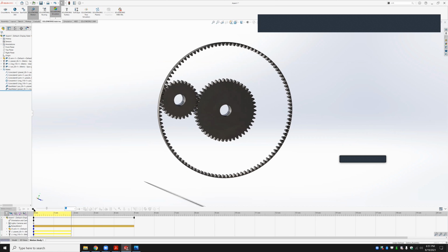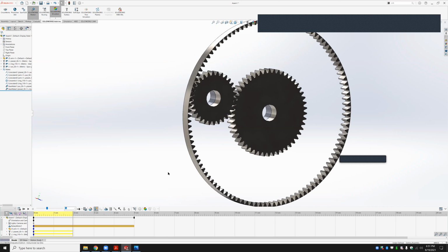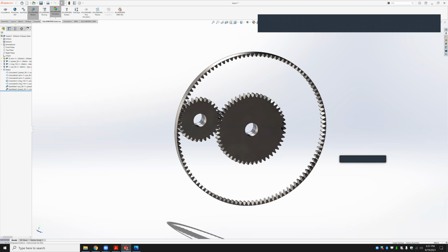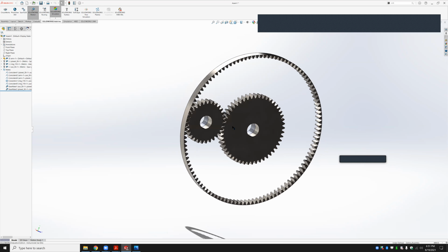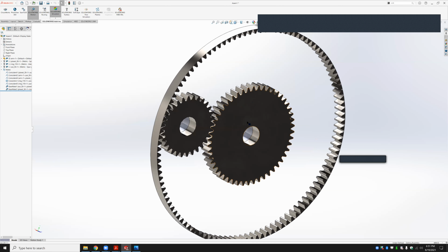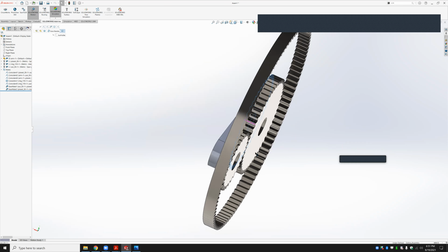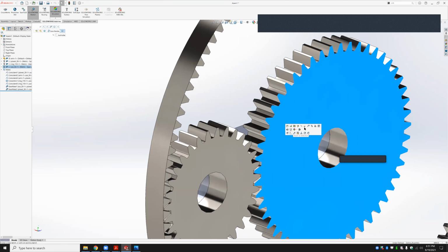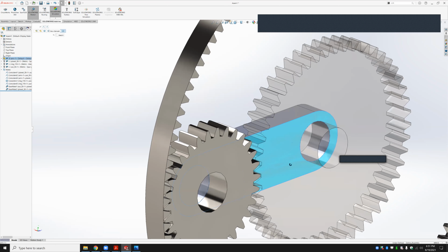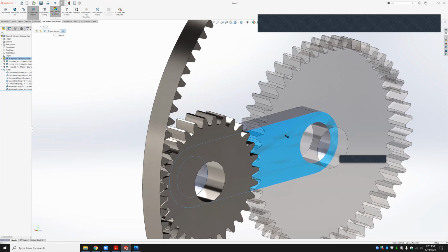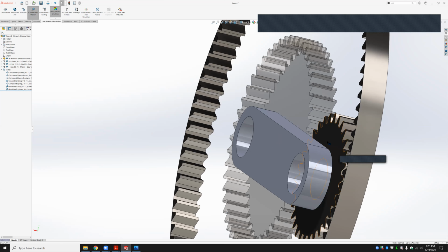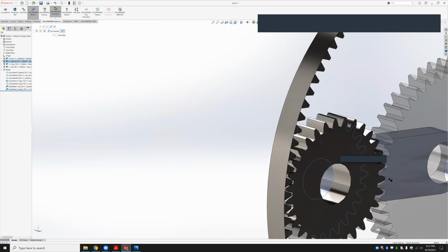So let me stop this and go back to my model. I kind of lost track there. The two sector ones to the arm? Okay. The concentric mates, do you do coincident mates between that surface and the inside surface of the arm? By the way, you can either hide or make parts transparent. So I'm going to change the transparency here. Do a coincident mate between the surface right here and the surface of your sun gear, and same thing with the planet and the arm right there.